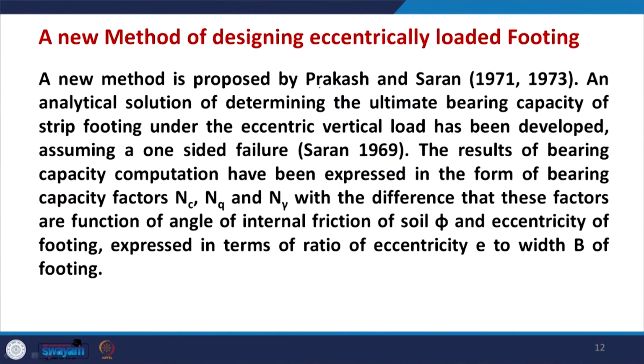This new method was proposed by Prakash and Saran in 1971 and 1973, and it is available in the books written by Shamsher Prakash as well as Professor Swami Saran. Let us discuss the method which they have proposed. An analytical solution for determining the ultimate bearing capacity of a strip footing under eccentric vertical load has been developed, assuming a one-sided failure.